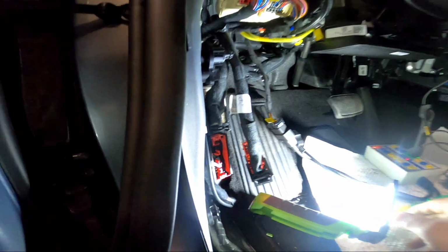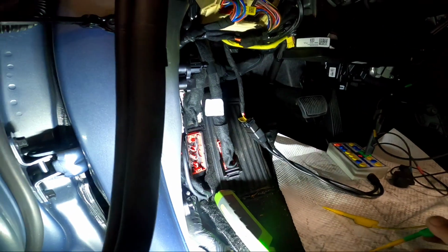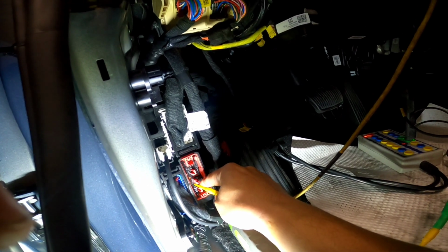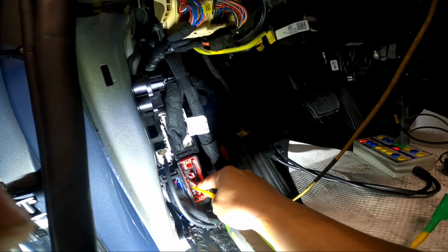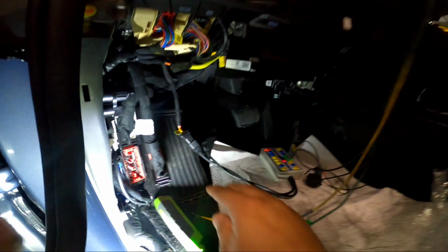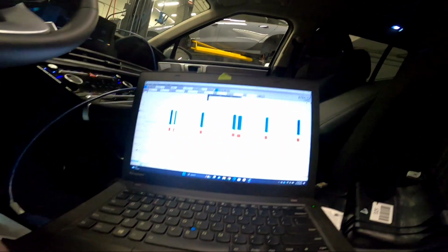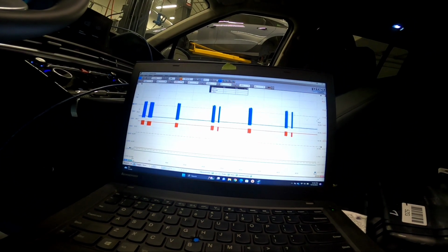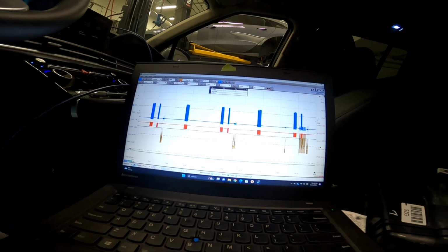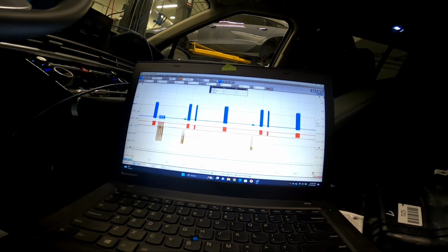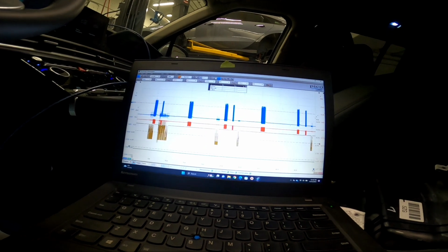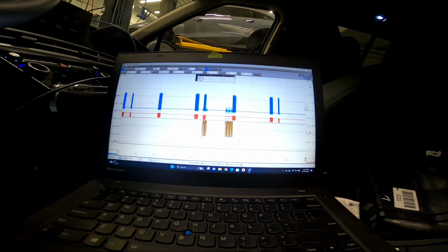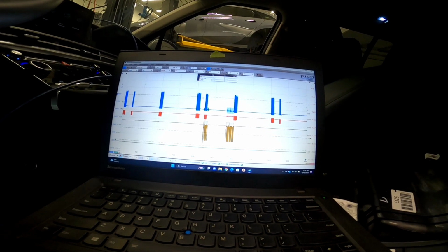So I'm going to poke the other end of it. I'm going to use our yellow first and see what we have there. The yellow is reading battery voltage, I can see it. So stop. Let's go to the yellow one. I'll just use one probe first. Where's that? There. Okay, so that's when I connected my yellow probe on my scope. Let's maximize that quickly and see our voltage reading there.